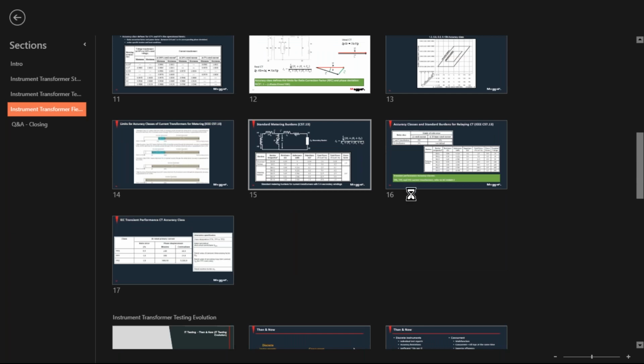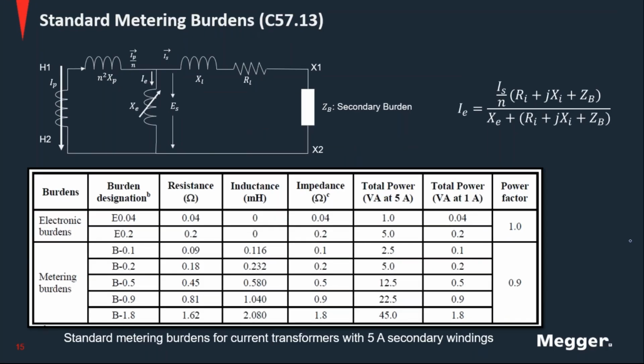It could be a change in the iron itself. Let's say there was a fault in the system. The fault drove the CT to saturation, and when the CT came back out, given that the voltage applied to the secondary of the CT during normal operation is so low, because at nominal current you will be talking about only a few volts applied to the secondary of the CT, then there will be some amount of remnant flux in the transformer. Just by not cleaning up the effects of the fault, that can increase the excitation current on the transformer.